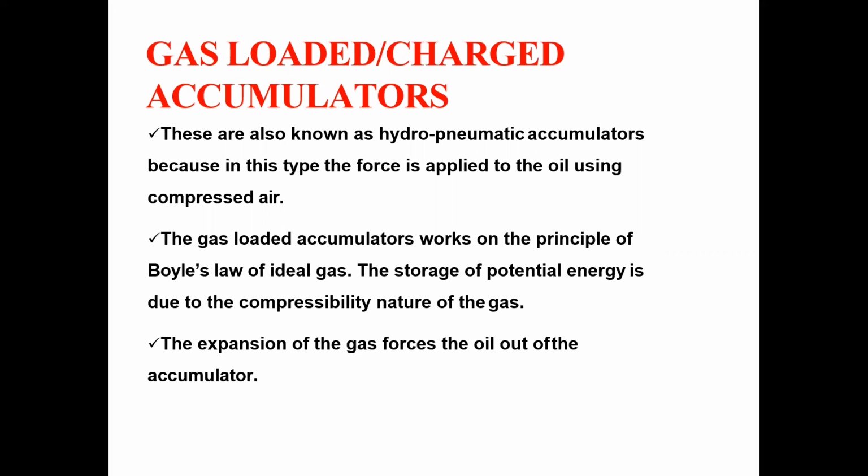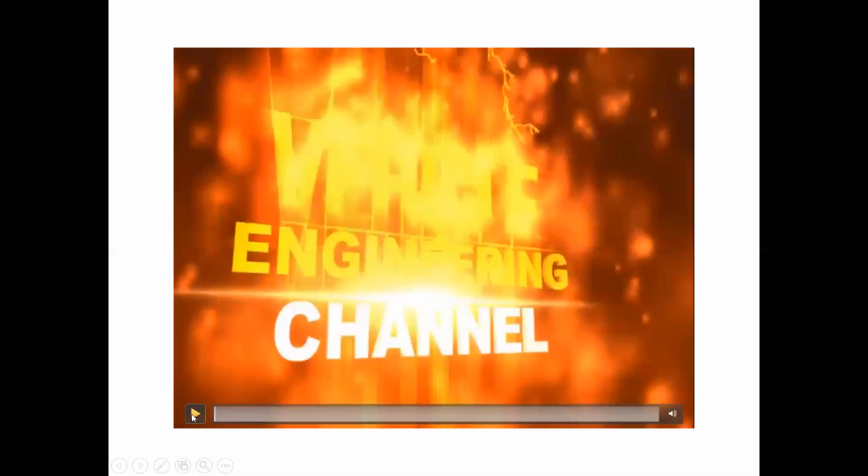What is the principle of Boyle's law? It says that pressure is inversely proportional to the volume. The storage of potential energy is due to the compressibility nature of the gas. Expansion of this gas pushes the oil out of the accumulator. You can see the working of this gas-loaded accumulator on your screen here.